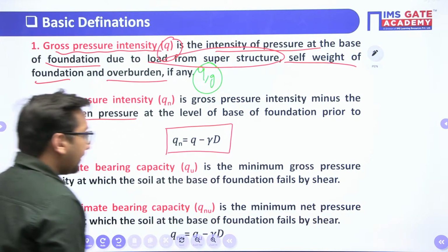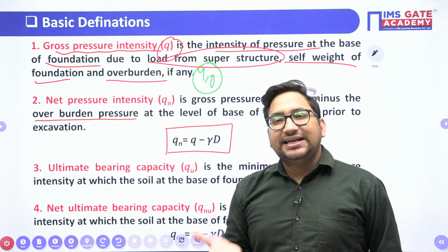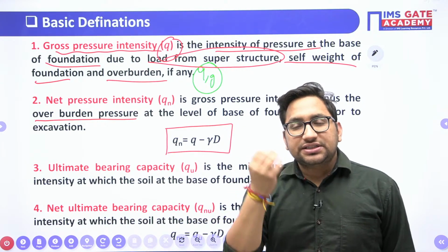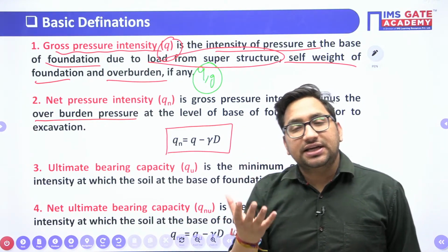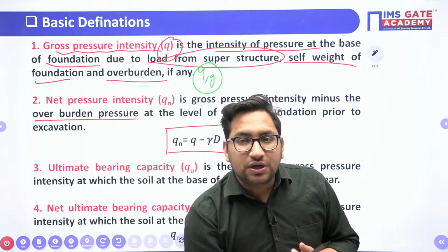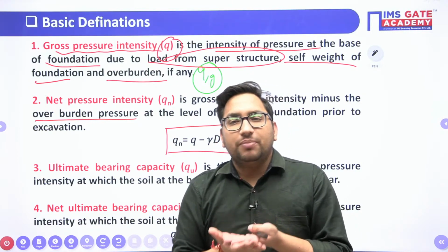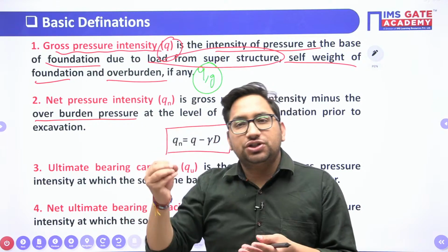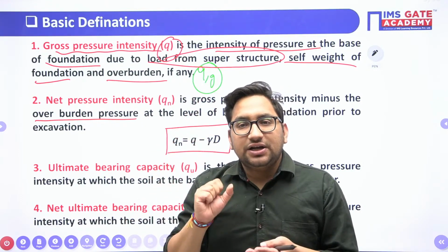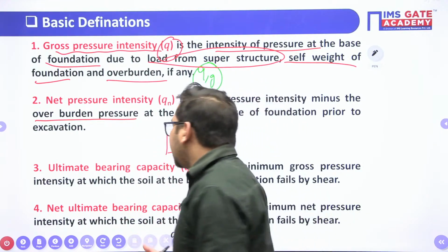Now try to understand, this is the particular stress value which is acting at the base of foundation. Now this stress value can be greater than the strength of your soil also, right? Let's suppose your soil can only support 50 kilopascal of pressure, and due to the weight of foundation, due to superstructure load, due to the weight of soil, you have applied 100 kilopascal of stress.